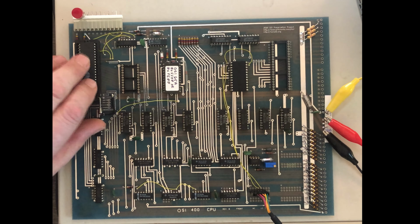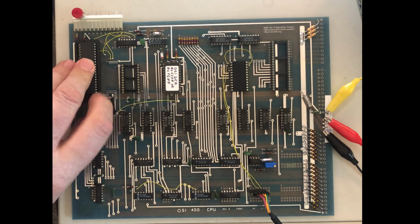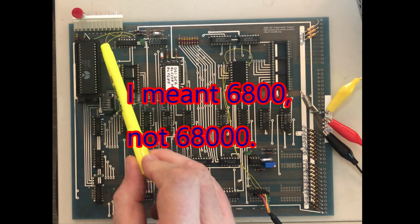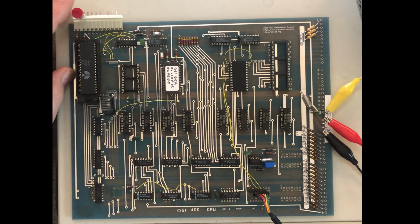The CPU, of course, is in a ZIF socket here to make it easy to change out. Like I said, this is a 6512 that's in here. So it's pretty much pin compatible with the 6501 or a 6800. There's a slight bit of difference up here, I think on pin 39. That really doesn't matter for what we're doing. And then there's a reset switch sitting right here. So that's really an introduction to the board.